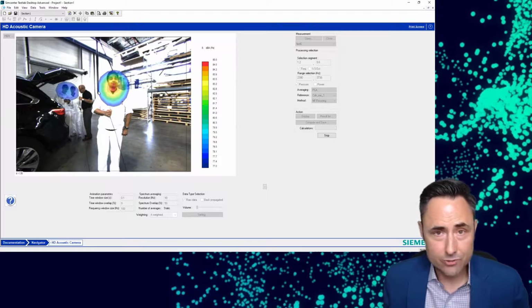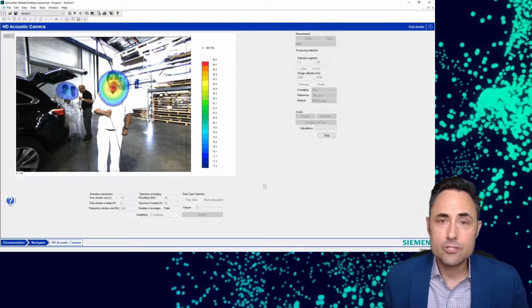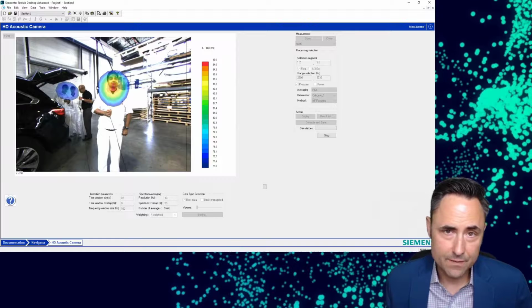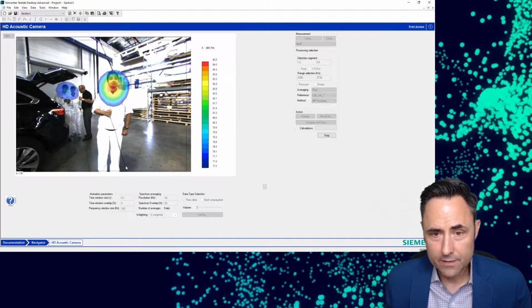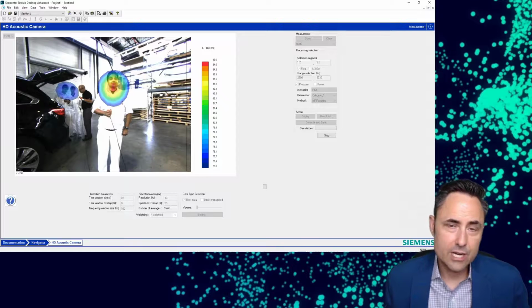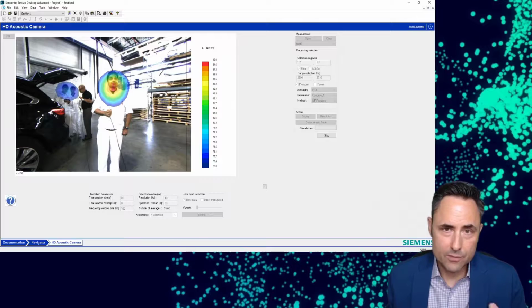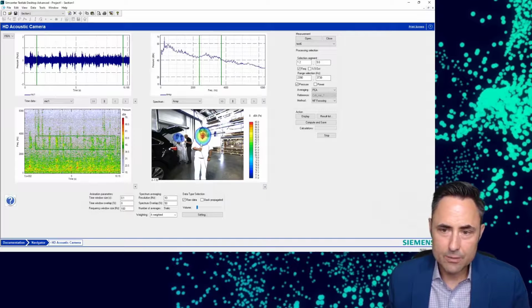Well, by adding an extra transducer or two, I can now intelligently process this data and separate these two sources making the same sound or frequency content. So you notice this guy's holding this cable. He's got a microphone. This guy's got another microphone. And so these are transducers I'm adding to my acoustic array. All right. So I measure with all my microphones in my array plus these two channels. And what I can do is I can see how much these guys are responsible for and how much this guy is responsible for by changing my averaging to something called coherence referencing.